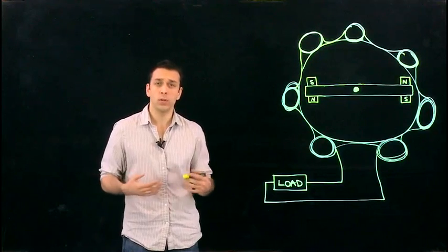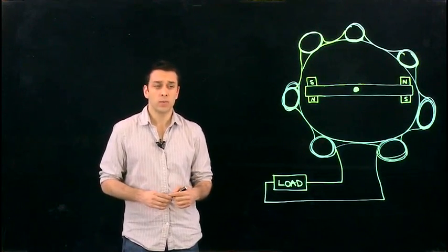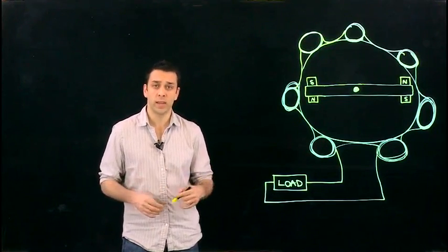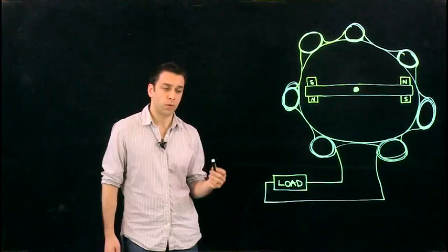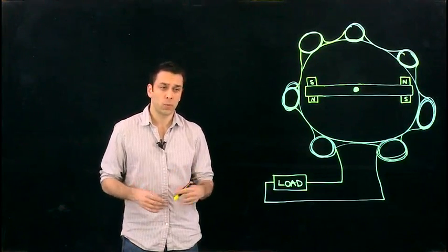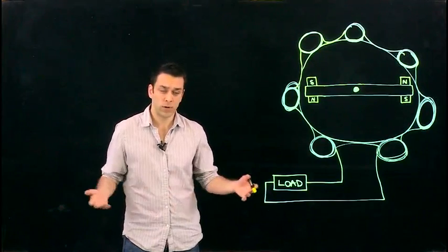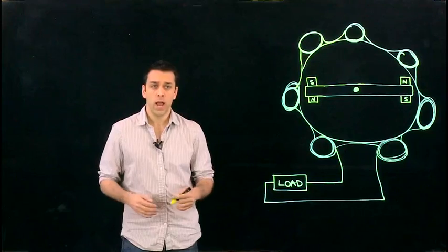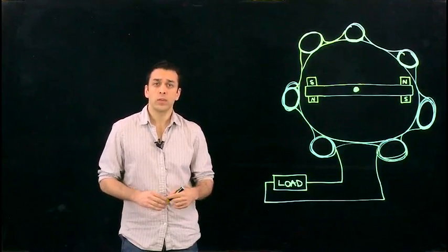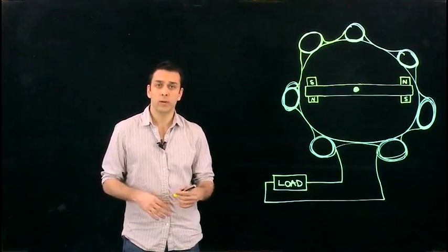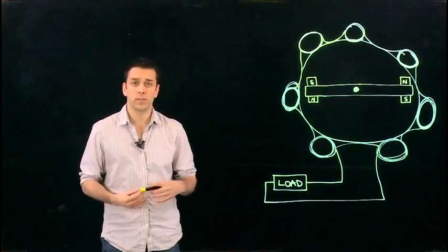We'll be describing how you can use the techniques that you've learned in this class to model the power grid from the point of view of, and by considering, its main components. That is, we'll be looking at how power flows from generators through transmission equipment, distribution equipment, through transformers, and off to power loads distributed across the grid. By looking at how all these major pieces of equipment function and how they connect together, you'll see how large-scale phenomena like blackouts can occur and how the grid can respond to different types of disturbances.